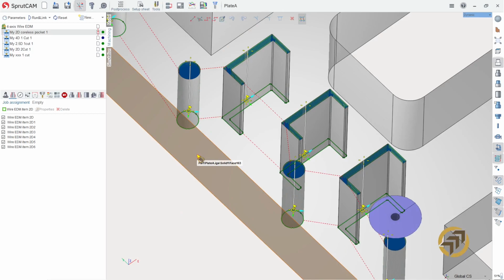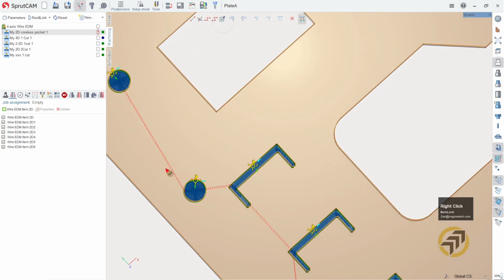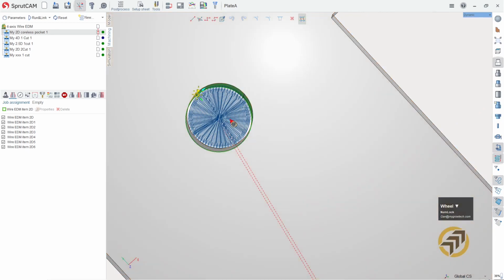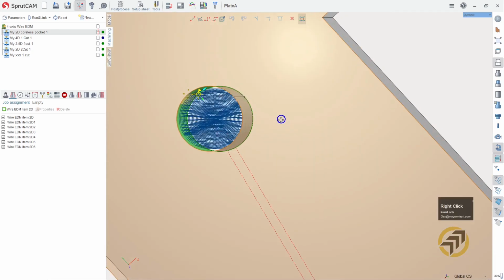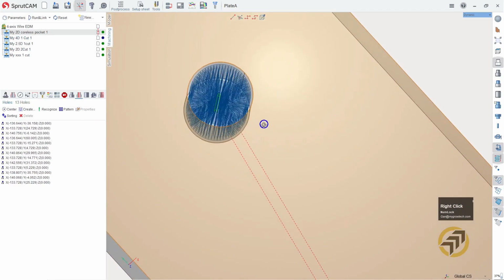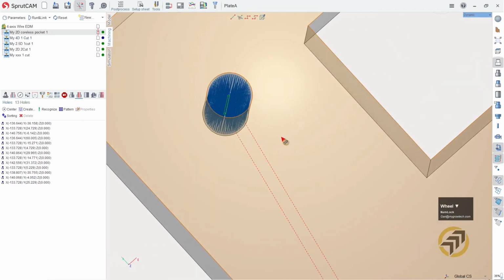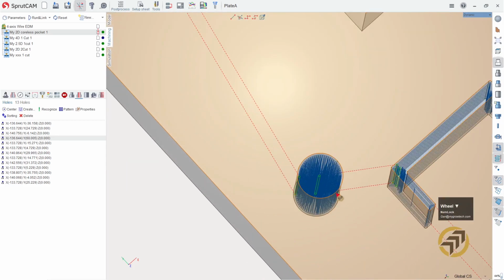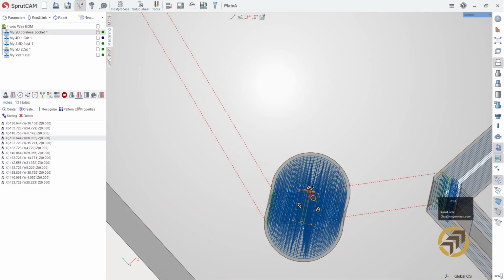And just in case you need the entry point for the drilling, to make the threading point, you can always come to this hole, and click here, use the Control key. This is the point.